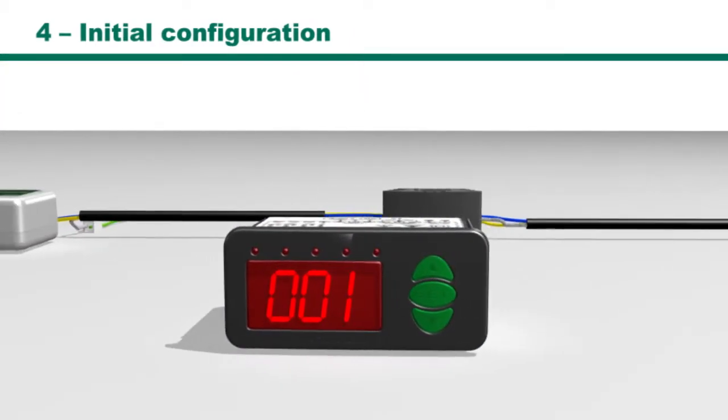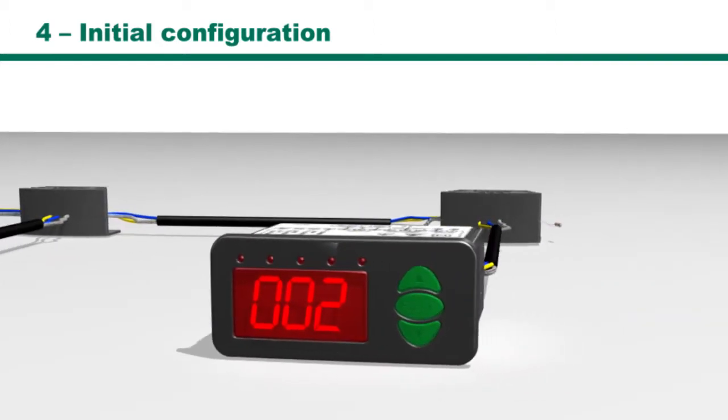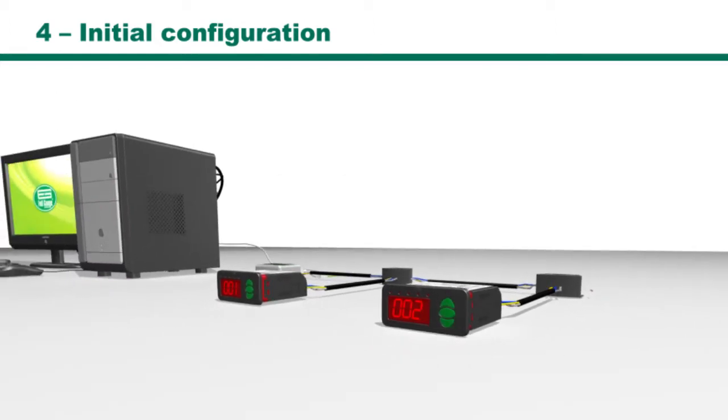Before you start configuring Sitrad, make sure the instruments have different serial address parameters. Refer to the manuals of the controllers to learn how to change the address parameter. Until the beginning of this training, the serial address is the last parameter of the settings list in all controllers.